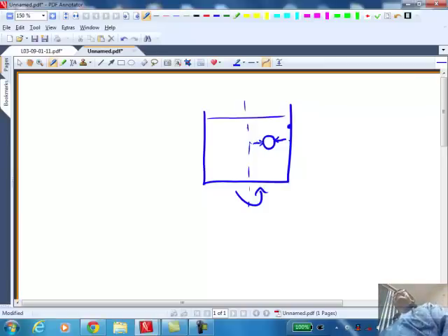And if the particle's density itself is higher, then there is the centrifugal force that it experiences, but it will always experience a net, what we call centrifugal buoyancy, buoyancy due to centrifugal force, that is pointing inward. Just like gravitational buoyancy is always pointing vertically up. The weight is pointing down, the gravitational buoyancy is pointing up. So it's the balance that decides whether the particle is going to sink or float. In the same sense, the centrifugal buoyancy will always be pushing the particle towards the center. But its own weight may cause it to go out. So it's a balance between these two that will decide whether the particle is going to be thrown out radially or in towards the center.